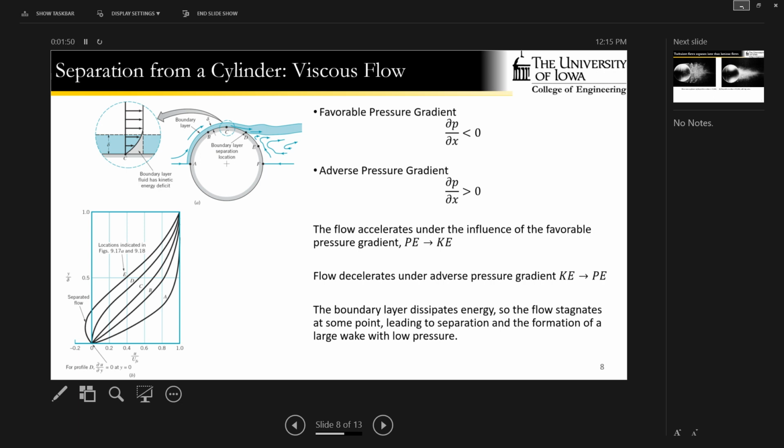So I want you to consider a boundary layer that's attached to a bluff object. Now, if I'm a particle at point A, I hit that leading edge of the body and I start to go around. That's generally going to create some acceleration of the flow. The flow is going to speed up as it's squeezed around the outside of that body. Now, Bernoulli tells us that as the flow speeds up, what happens to the pressure? It drops.